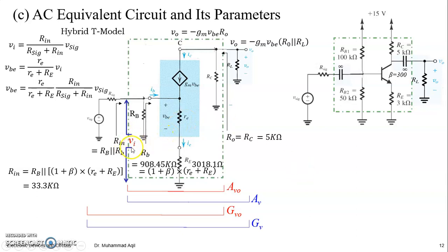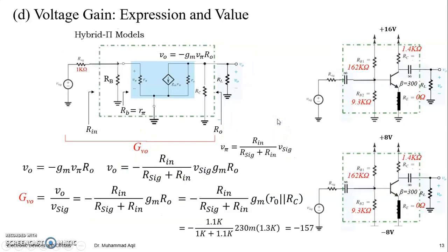So why are we discussing Vi here separately and did not discuss it in Rpi? We had discussed that with the previous common emitter amplifier without emitter resistance example. At that time we said this would be your input resistance, the parallel combination of this and this, and whatever voltage appears here will be Vin, the voltage at the input of your stage.